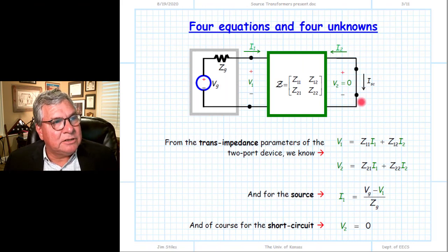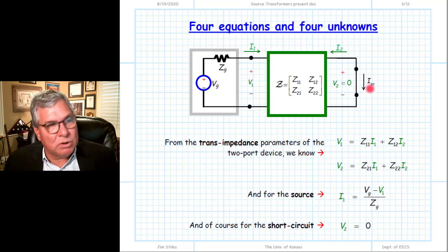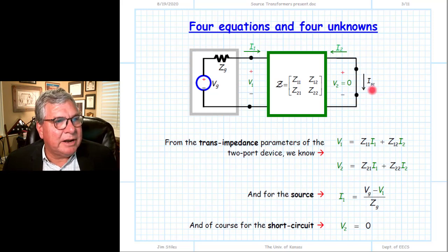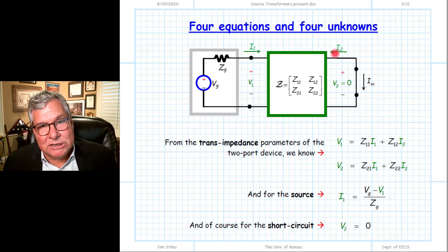So we connect a short circuit here to port 2, and we define a short circuit current. In this case, we define short circuit current as positive when coming out of the port, and so through the short circuit from top to bottom. That's important so we'll get the right result for a Thevenin equivalent. We're trying to figure out what this current is, and notice this current will simply be the opposite of whatever I2 is. We simply need to solve for I2 and multiply it by -1.